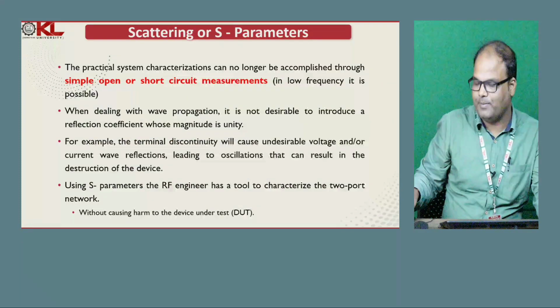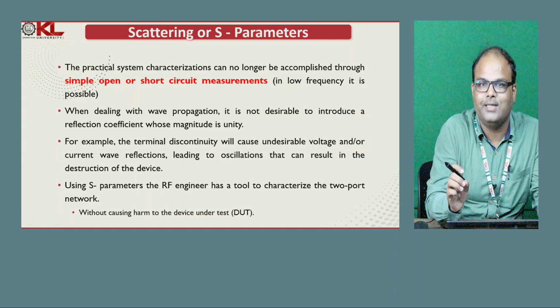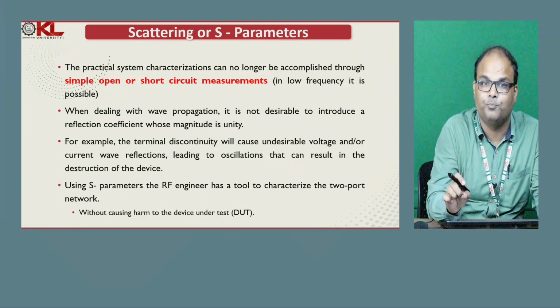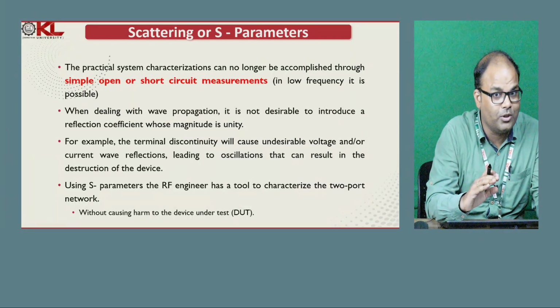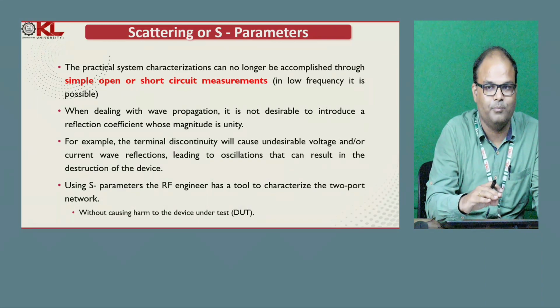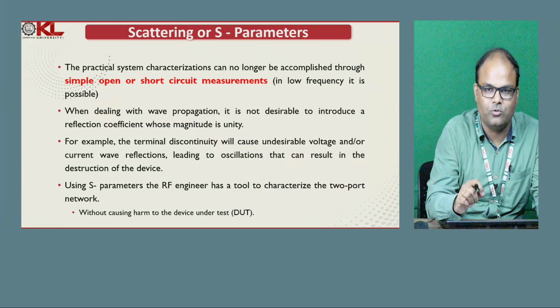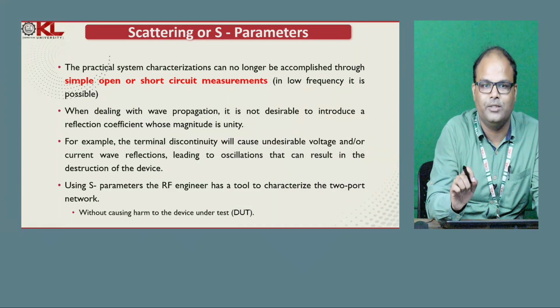If you are thinking about S parameters, practical system characterization can no longer be accomplished through simple open or short circuit measurements, as in low frequency applications. When you are thinking about wave propagation, it is not desirable to introduce a reflection coefficient whose magnitude is unity.